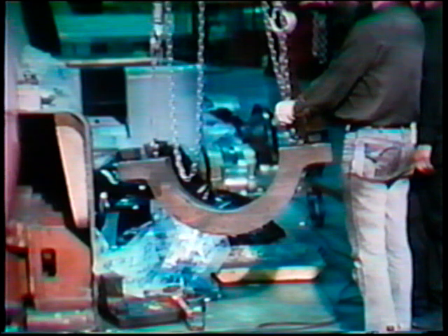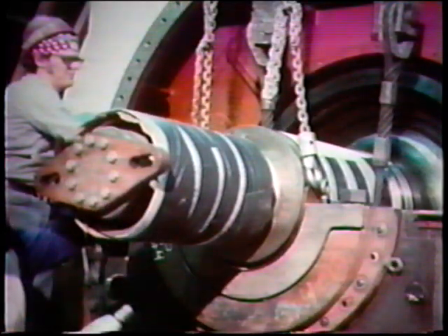One way to support the rotor is to use a jacking device mounted on the lower half of each end bell. The device jacks the rotor up slightly so it no longer rests on the bearings. Then, the lower half of each bearing can be rolled out from under the rotor's shaft. The next step in disassembling the generator is to remove the rotor.